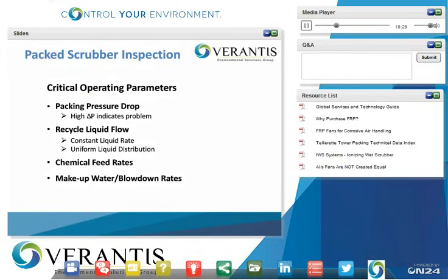So there are a number of critical operating parameters for optimum performance of the packed section. Typically, most scrubbers will have some measurement of packing pressure drop. That's an indication of the pressure loss from the inlet gas to the outlet gas due to the packing, due to the airflow passing through the packing. High delta P indicates a problem, and that's most typically due to some type of fouling. We'll talk about types of fouling in a few minutes.